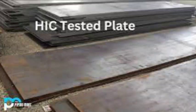I will ask. Yeah, then when you do a welded pipe with plate, then again the welded pipe you need to undergo HIC testing. Okay, now seamless pipes are only excluded. Welded pipes, since they are made out of plate, you have to do HIC testing for welded pipes.